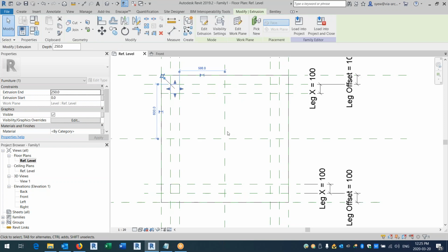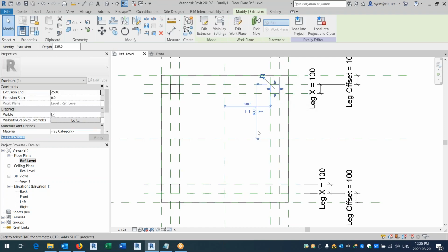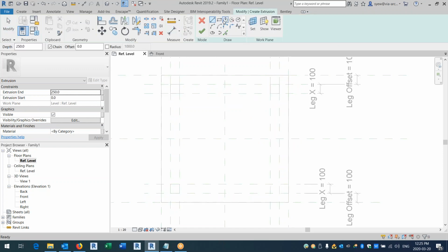What I typically recommend users to do is that I always keep all of this independent from each other so that they don't clash with each other. You could do it in one shot, but the only problem is that once this table hits 0, let's assume that this thing is touching that, then the whole family breaks. So just keep in mind what you're doing.